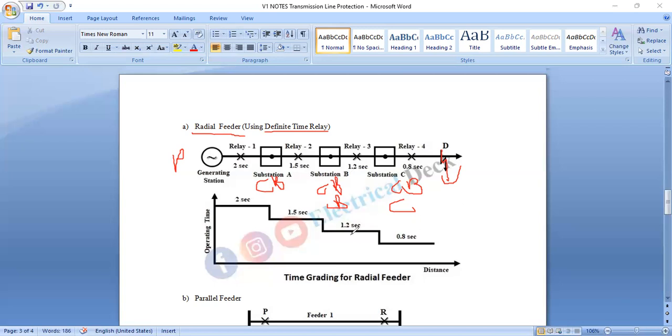If a line to ground fault occurs in the system in a section nearer to the transformer or source, the amount of fault current will be more. Here the fault current is maximum, because line impedance is less.